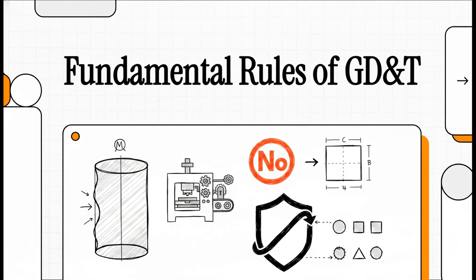In our previous lessons, we laid down some of the basic terminology, but today we are going to explore a foundational concept that will completely shift how you think about engineering drawings. We're going to uncover exactly why size alone just isn't enough to control form, and how ASME rule number 1, also known as the envelope principle, solves one of the most critical, headache-inducing manufacturing problems out there.